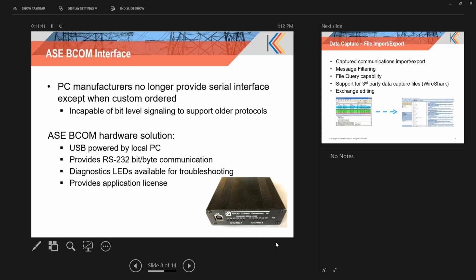debug and troubleshooting, because in certain scenarios, even though you've defined a configuration for testing and it appears that you're actually sending information to a destination device, without LEDs it's very challenging to determine whether or not the message was received. And these LEDs are pretty handy in identifying communication setup scenarios where a parameter may not have been defined correctly, or they can support a conclusion where a device received a perfectly defined message and it's not responding accordingly.